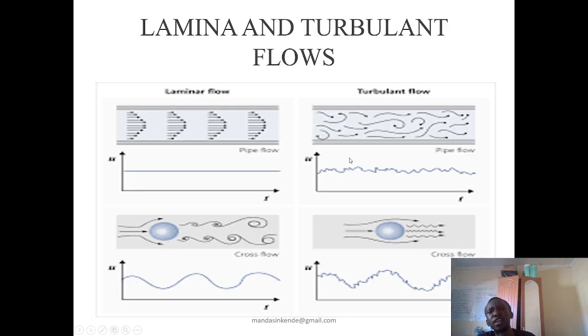Before we go into the discussion of the vortex generators, first I have to explain laminar and turbulent flows. Laminar flow is when the streamlines are parallel to one another, while in turbulent flow, they are randomly dispersed even as they go in the direction of flow. Now, you observe that in the flow that is laminar, the detachment happens earlier compared to a turbulent flow. That is because in turbulent flow, despite it being random, there is more energy in this randomness, and therefore it is more difficult for the airflow to detach from the surface.